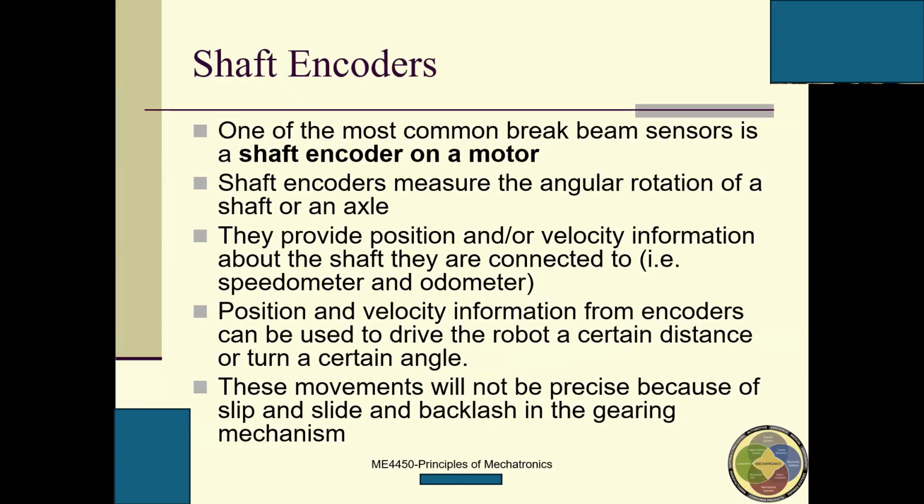Any questions regarding this slide? We have learned about backlash, right? So who can tell me what backlash is? Well, there's a little bit of movement in the gears before it actually starts turning, and then you get an inaccurate reading on the scale compared to it actually moving. Yeah, this is backlash.